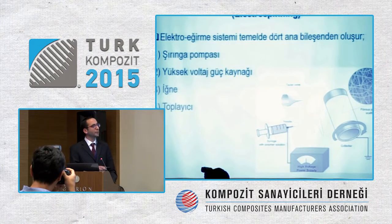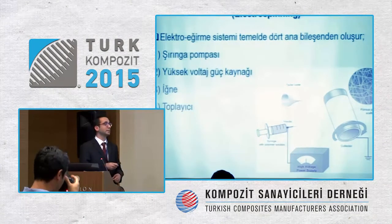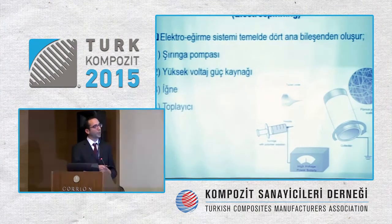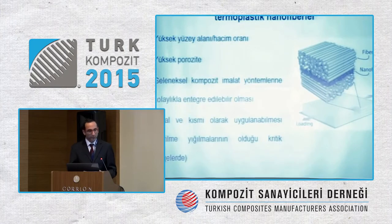As the voltage gets bigger, the solution forms a Taylor cone structure after a certain voltage. Then it creates a jet, and during the flight, the solvent evaporates, and we create the nanofibers over the collector.